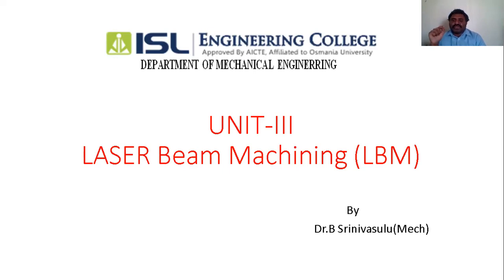So we convert electric energy to light energy, then this light energy is converted into heat energy. Radiation is formed with this light amplification. The radiation from the ruby crystal is focused, falls through the focal length onto the material, and the excess material is removed from the workpiece. This is the basic concept of laser beam machining.